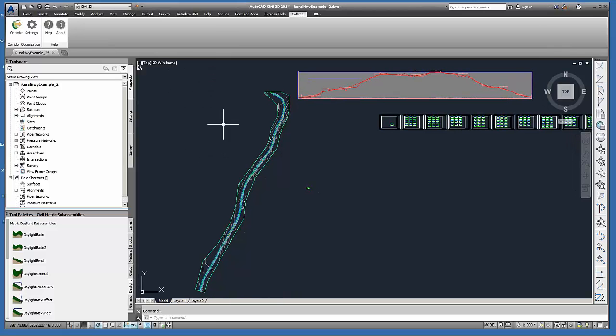Anyway, what I've got here is a Civil 3D project. It's a 10-kilometer rural highway, and as Cam mentioned, the key things to bring from the Civil 3D project are the existing ground surface, the alignments, and also the cross-section. And it's usually the cross-section that causes the greatest amount of problems. In the Civil 3D world, we're talking about assemblies and sub-assemblies. It's complicated stuff, and there is no LandXML format that supports that.